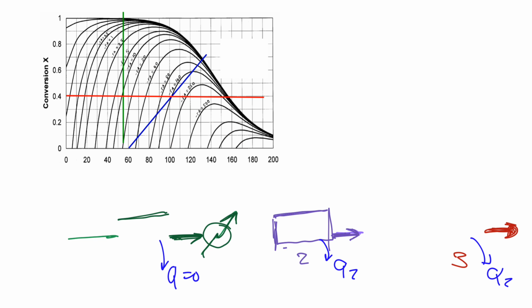I'm just going to show you with the pointer now. Start in reactor 1, increase adiabatically to the conversion in reactor 1. Cool down to the inlet temperature of reactor 2, increase adiabatically to achieve the conversion in reactor 2. Decrease to the inlet temperature of reactor 3, and then finally go to my final requirement of the conversion that I really want to achieve. So let's say the overall conversion that was specified here was 90%, based on the inlet flow rate of A.